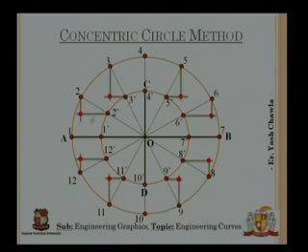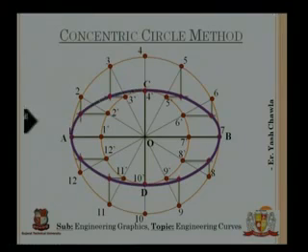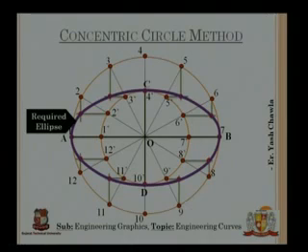These points are the points on the ellipse, and C, D, A and B are also on the ellipse, so we need not draw anything extra for that. Now I'm again going to start from C and join these red points in a clockwise manner, and I'm going to get my ellipse. The required ellipse is here by the concentric circle method. 2 more methods we are going to discuss. Don't worry, I'm not going to take any break.